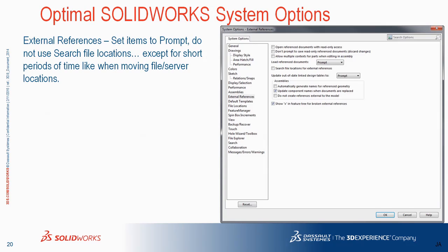If anybody looks into, Adrian can speak more about it as well, the recursive searching for files. Yeah, the recursive searching for files will absolutely kill you if you're putting items in there in the external references list. The search mechanism that SOLIDWORKS uses is built to get a file into the system regardless. And to do that, it searches in a lot of places, and a lot of places, believe it or not, that don't actually exist. It makes them up as it goes through the search path that you set up. It makes up places to look and then tries. So avoid it at all costs.